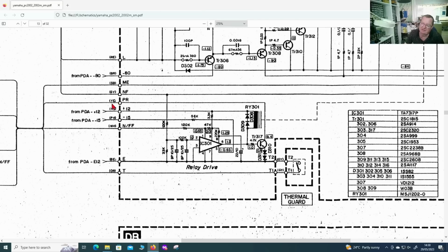It actually connects the cathode of the LED to ground, basically, via these resistors. The other end, the anode, is fed from 12 volts via resistor, so the LED turns on. We're in protect mode. When this chip switches the relay on, so we're not in protect mode, there's now 0 volts here. It's below the voltage of the emitter. This transistor turns off, and we now effectively have 12 volts on here, the same as the other end of the LED, so the LED is off. That's how it works. I did say it's a little bit more complicated than just an op amp.